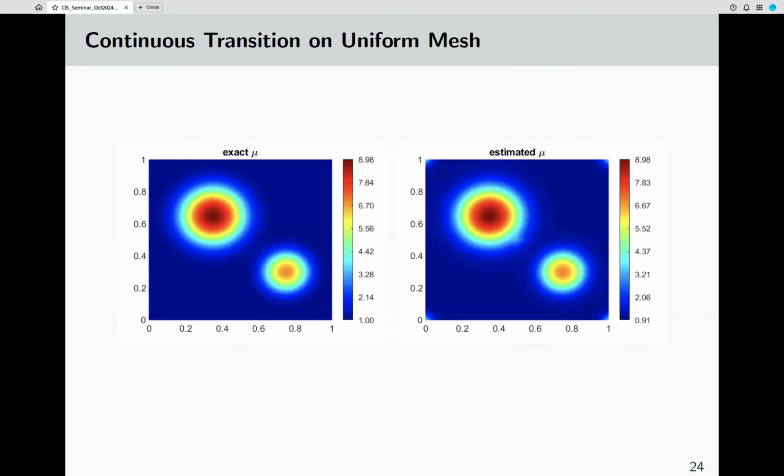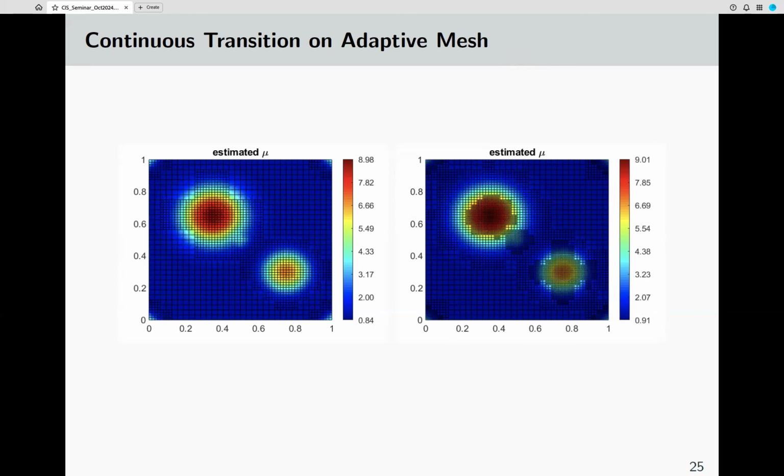So we can say that we can recover these quite easily, even using uniform meshes, that means all same squares, right? That works. And here we are just using the adaptive mesh refinement technique again. Because the changes are gradual, it's refining in some places more and in some places less, where the solution is not changing too rapidly, but it doesn't make too much difference. We can still recover these using uniform meshes.